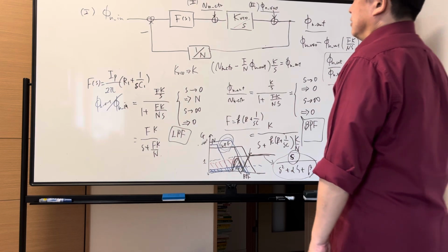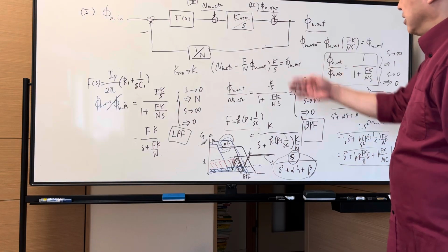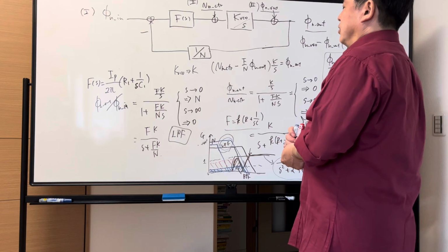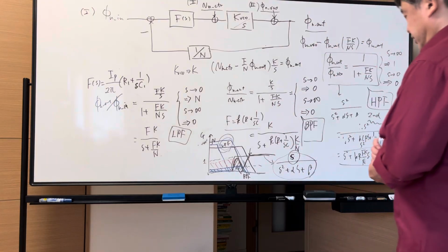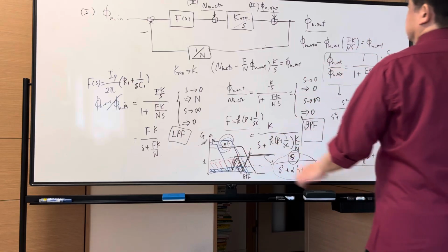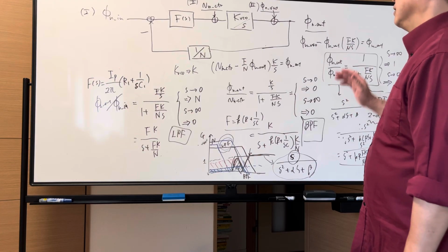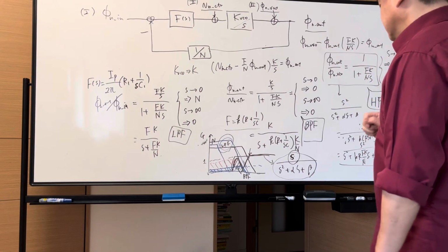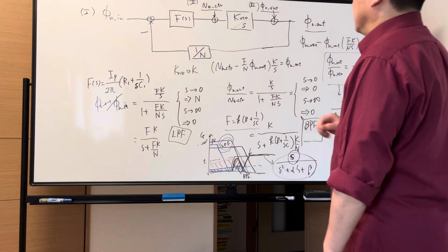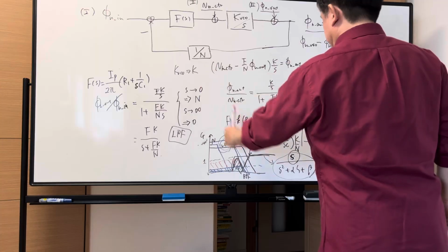So if you have a very low noise input clock and digital circuits here in the PLL, like the case of an LDO having very small voltage difference noise, you can easily set the loop bandwidth higher and suppress the VCO noise and get very good output quality. But in reality, we have other parts, so we must optimize the loop bandwidth of this PLL.